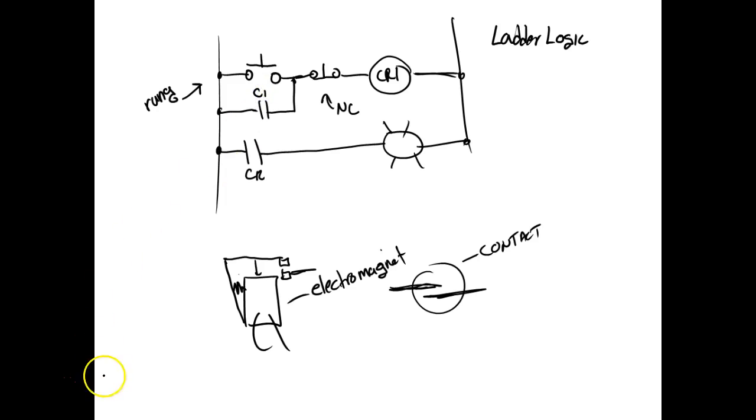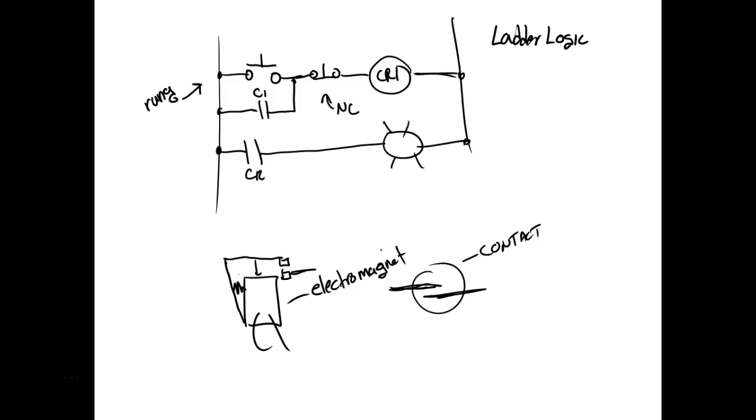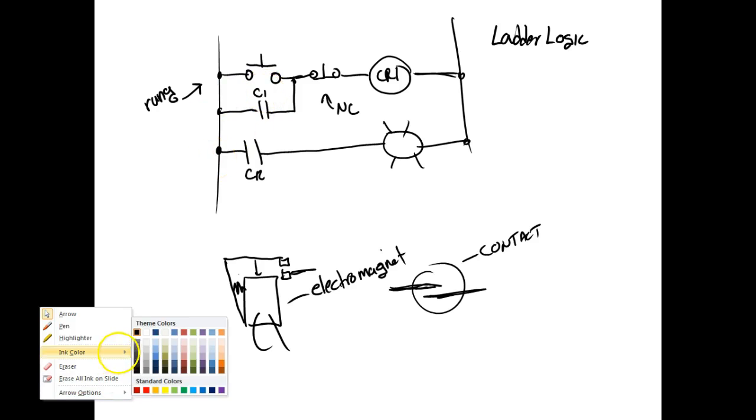So in industry, you see a lot of push buttons. You don't see many switches because push buttons are easy to operate, right? You understand that, and they're easy to operate with gloves on. These little switches that we run into, they would be what? Harder to operate, and you've got to figure out what's going on. So what we would do with this one, this is a pretty standard circuit right here. This basically is a memory circuit.